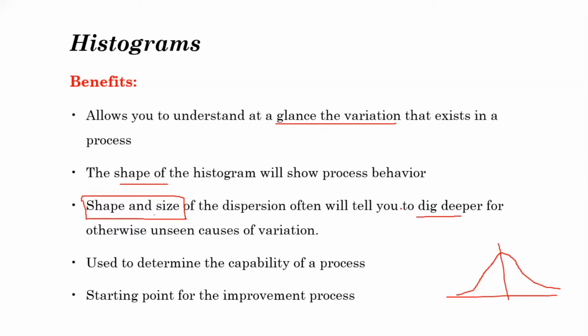Then the other thing, if the process is normally distributed, but you have too many rejects, then it would direct you to analysis of process capability. We'll look at what we mean by process capability in the subsequent chapter, but basically it would enable you to be concerned about process capability. But if the process is not normal in the first place, you would not go to process capability. We would look at this assumption when we talk about process capability as well.